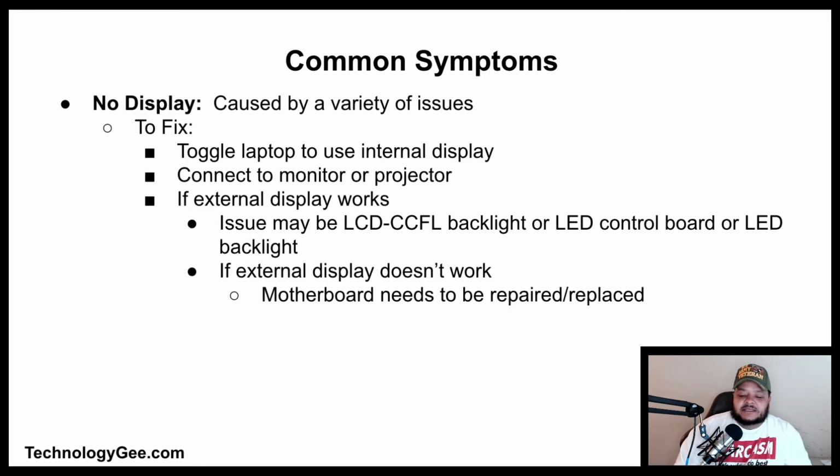Now, to fix some of these issues, what you will need to do is just try toggling the laptop to use an internal display. Try connecting it to a monitor or a projector. If the external display works, then the issue may be with the LCD CCFL backlight, the LED control board, or the actual LED backlight. If the external display doesn't work, then the motherboard may need to be repaired or replaced.